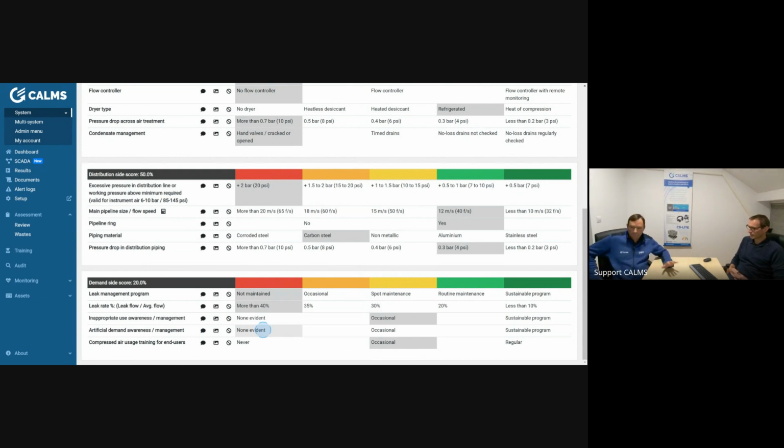Some of the areas are very hot, because we have smelters, we have the continuous caster, and then the milling machine, and the rest of the mills. I don't like to get there. It's just very, very hot. I think it's also difficult to identify this, virtually impossible. It's so loud in there, you can't hear anything, and they don't stop. We will try to use an ultrasound device from a distance. We will just try to measure it, estimate the leak rate from a distance. So maybe this would help to identify this.